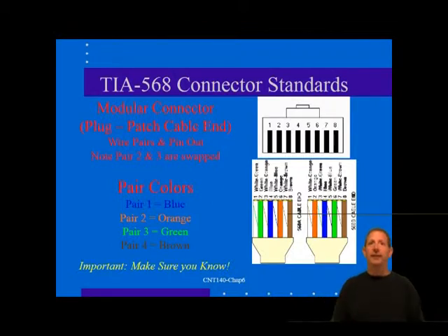However, it seems that the A pattern originally was not used as much because it was different from the pattern that had historically been required for telephone use. Now that most manufacturers offer both, you are free to follow the TIA's preference or your own. So what happens if you use one pattern on one end of a cable run and another on the other end? Most LAN network connections will fail, and telephone connections that require two pairs will also fail.